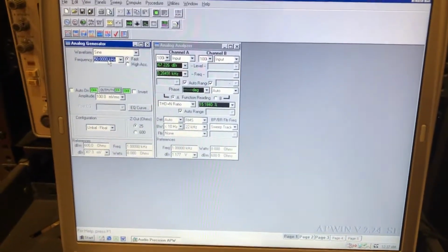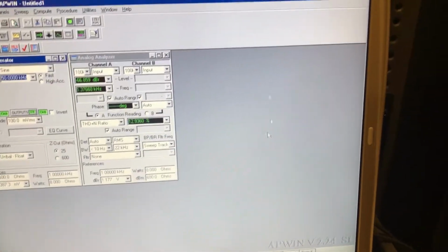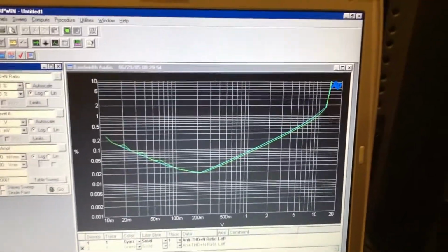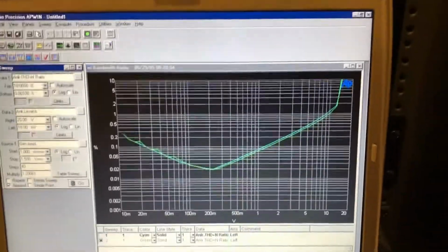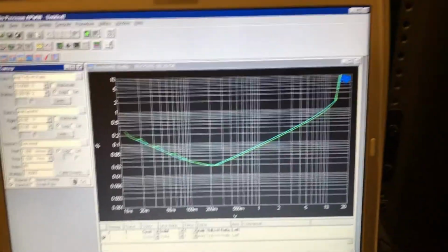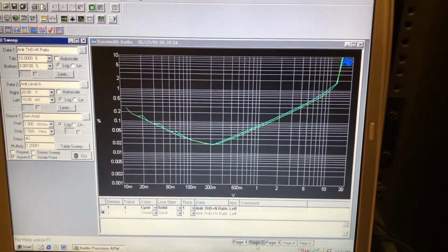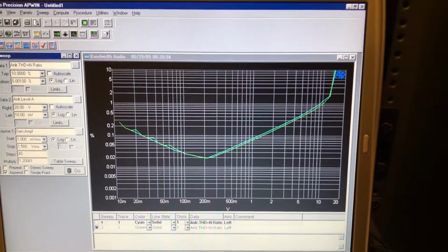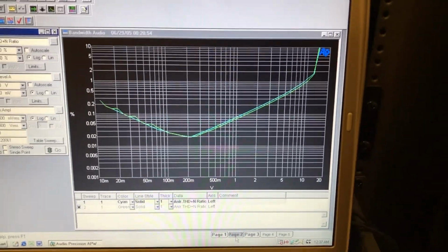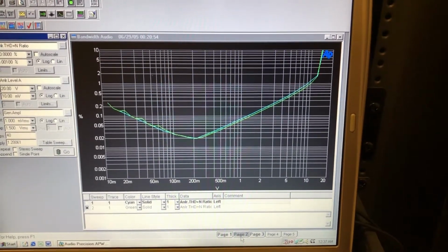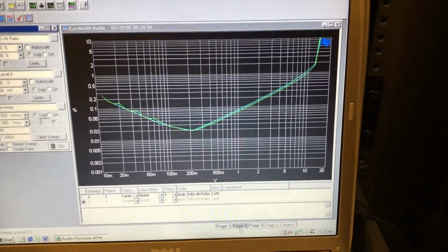And like I said, where I wanted to test next was this stage and compare it. What I will compare, I guess, is the THD versus output waveforms at 1 kilohertz. I'll make a comparison across a couple different tubes. So I'll take a weak 6AH4 and a strong 6AH4, and I'll plot these curves. And then I'll also do a comparison of my 15 milliamp operating point, as well as a recentered 20 milliamp operating point, and see how the THD versus signal compares. And that should at least give us some relative comparisons that will be useful, and then we can make some decisions on how to adjust the stage now and down the road once we connect the driver.